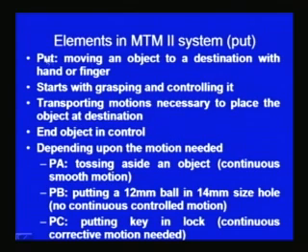The put is another element, which involves moving an object to a destination with hand or finger. It starts with grasping and controlling the object and the transporting motions necessary to place the object at the destination, and ends with the object in control. Depending upon the motion needed, the put element is classified as PA, PB or PC.